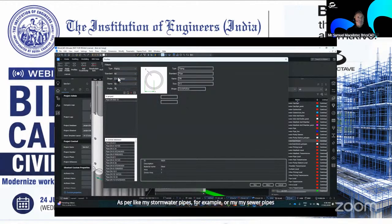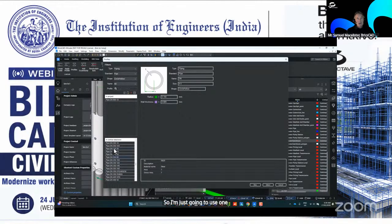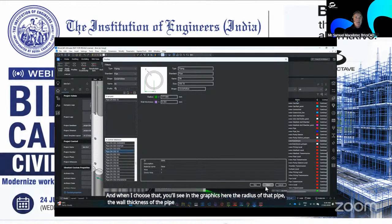Here, I'll filter through the categories in my profile database, standard pipe, and I can choose to duplicate one of these or create a new one, or I can use some of the ones that are in the database here. So I'm just going to use one of the larger diameters. And when I choose that, you'll see in the graphics here the radius of that pipe, the wall thickness of the pipe, and the materials.